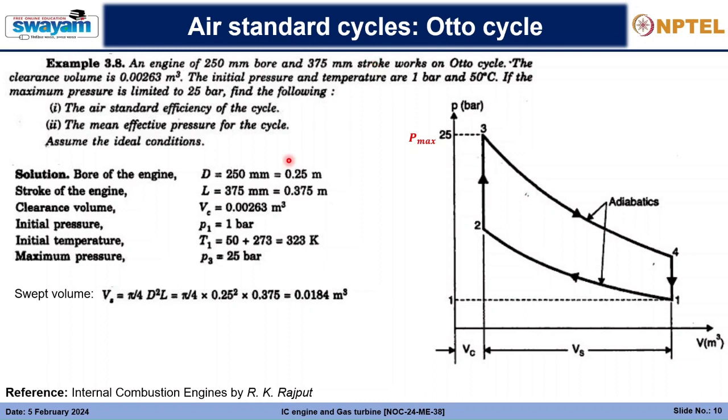So you directly use the L as 375 mm here. But if you are given the entire cylinder length, that is from the piston head to the bottom dead center, that would mean differently. So you will not get the stroke. So here you are getting the stroke volume Vs directly, and you are given separately the VC. Accordingly, you will get the total volume.